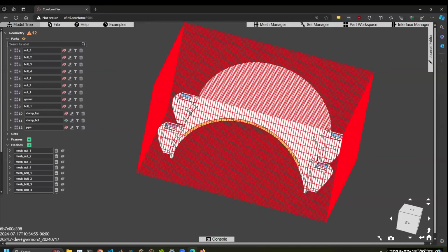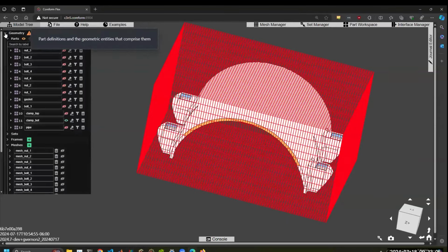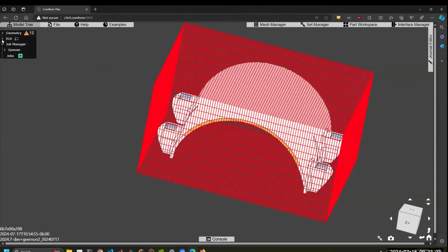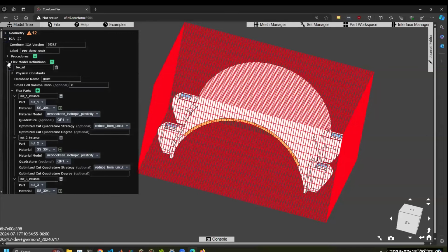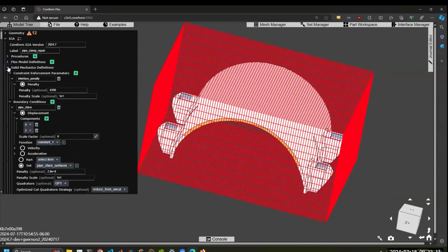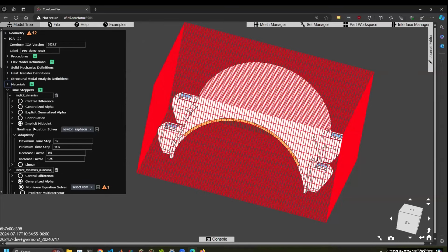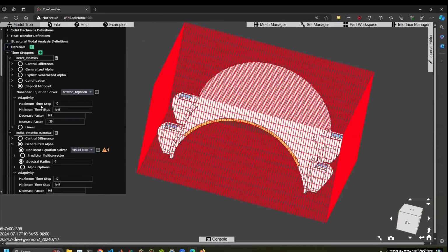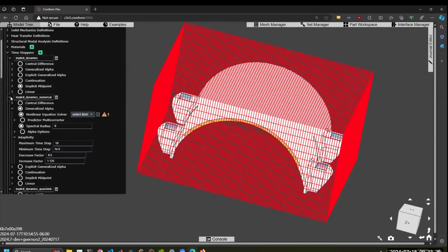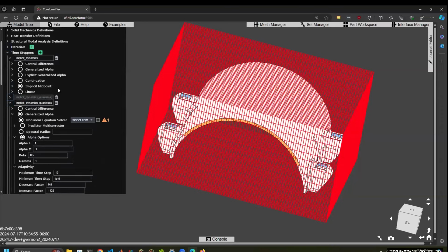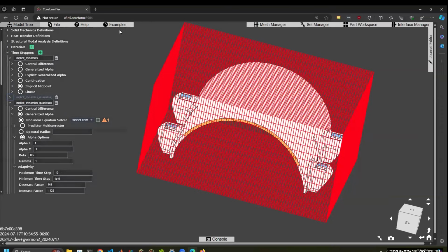And then from the solver standpoint, let me pull up the solver real quick. In this case, what we have chosen is actually an implicit dynamic solve based on Newton-Raphson, but we can also use our static solver as well. We have multiple solver settings in here for implicit dynamic, various implicit dynamic with quasi-static and fully implicit.